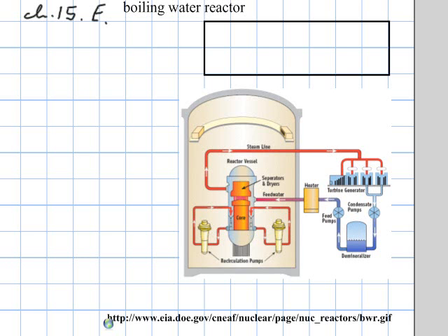pressure. After the steam does the work of turning the turbine of an electric generator, the steam is converted back into water in a condenser at 40 degrees Celsius, the temperature of the cold reservoir. To keep the condenser at 40 degrees Celsius, the rejected heat must be carried away by some means, for example by water from a river. The plant operates at 3/4 of its Carnot efficiency, and the electrical output power of the plant is 1.2 billion watts. A river with a flow rate of 100,000 kilograms per second is available to remove the rejected heat from the plant. Find the number of Celsius degrees by which the temperature of the river rises.